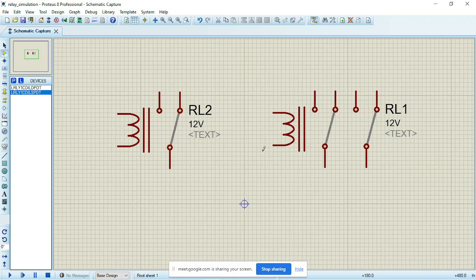So these are the two major relays that we'll be using most times. Double pole, double throw. That is this one, which means you have double pole, and once you trigger the relay, those two poles will move together. So once you trigger your relay, these two commons, you have common here, you have common here, will move together to normally open at a time.